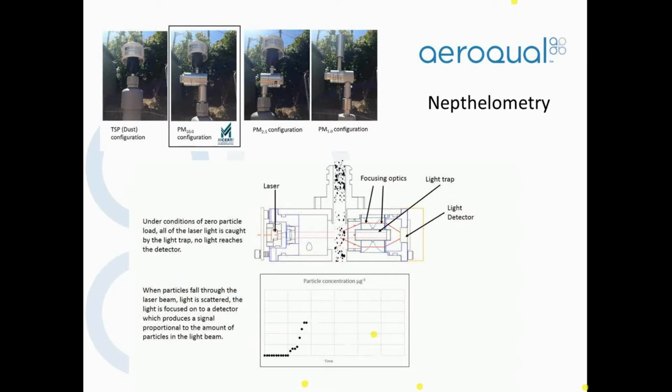At this point, it's a good idea perhaps for me to just reference one of the limitations of the optical methods. As the illustration I've showed you, I haven't really talked about what the particle matter is, but one can visualize what might be happening to particles of different colors or opacities or even morphologies as they fall through the laser beam. So to give you an example, if we're trying to measure particles of size PM10, we are making some assumptions when we're using an optical method.